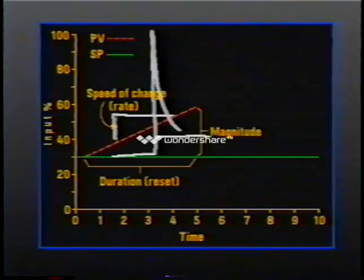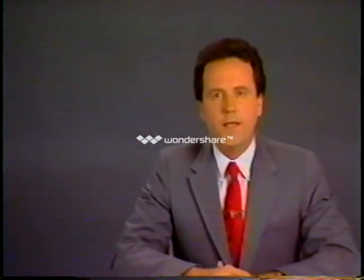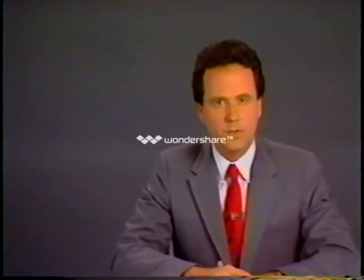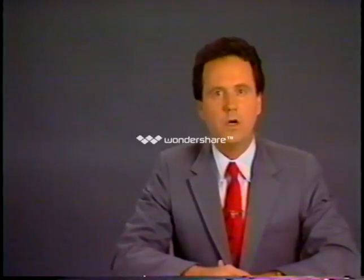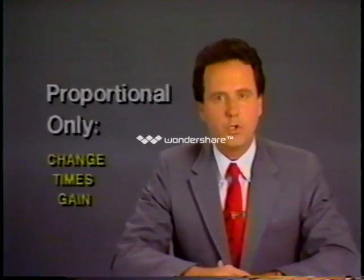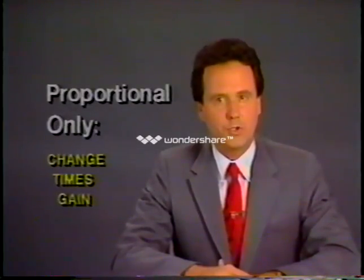For this reason, many controllers are actually designed to consider the rate as a function of time and the change in the process variable, rather than time and the change in the error between set point and process variable. This approach eliminates the problem of a large output spike caused by a change in the set point. The output of the controller is, of course, the signal that will determine the degree to which inputs are altered in order to achieve control of the process. In a proportional-only controller, the output is a function of the change in error and the controller gain setting.